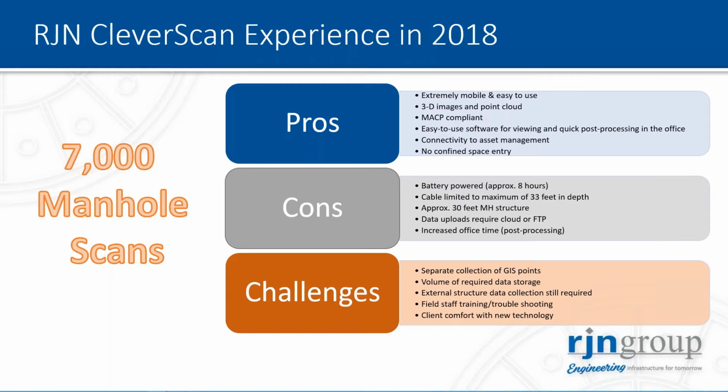The limitations are, before any inspections are done, they have to make sure that the battery is fully charged. It only allows you for a 1 day's inspection, 8 hours. The other assurance that you want is to make sure that you have sufficient portable data devices so that as you're collecting the information, you can have it saved on site.